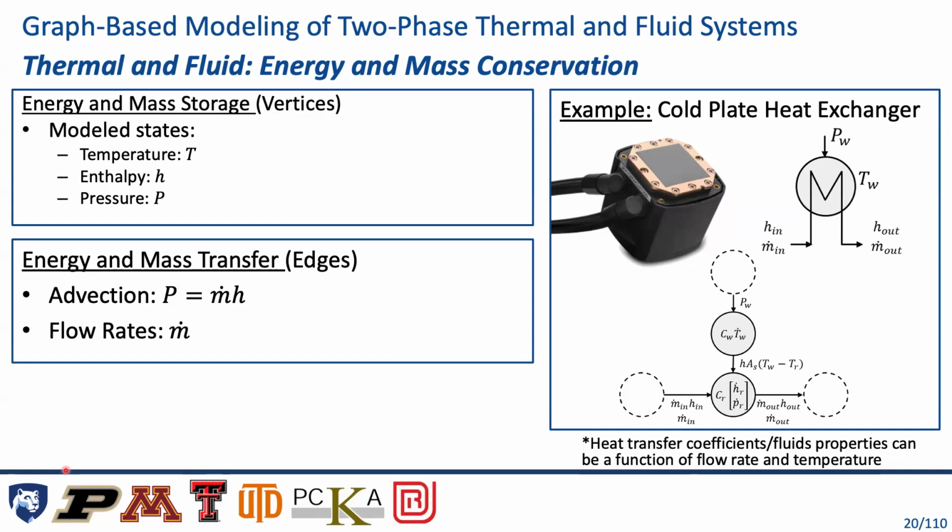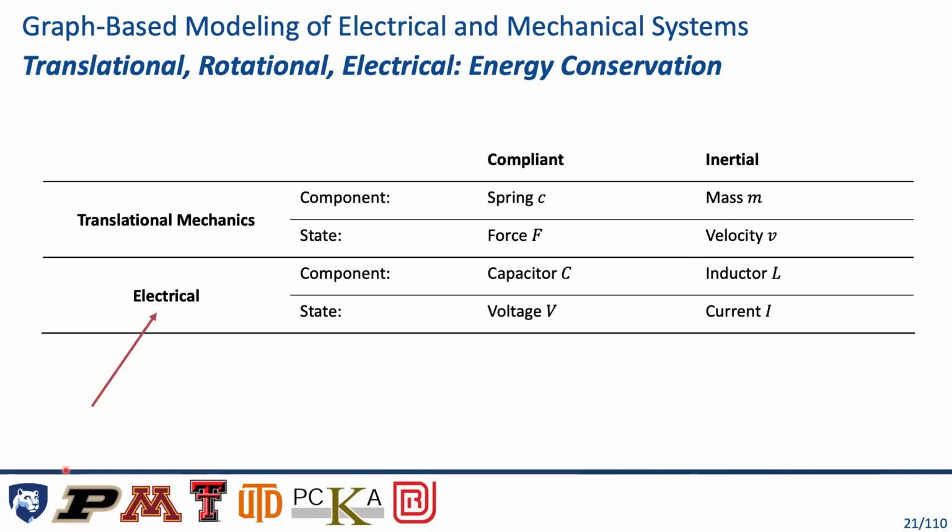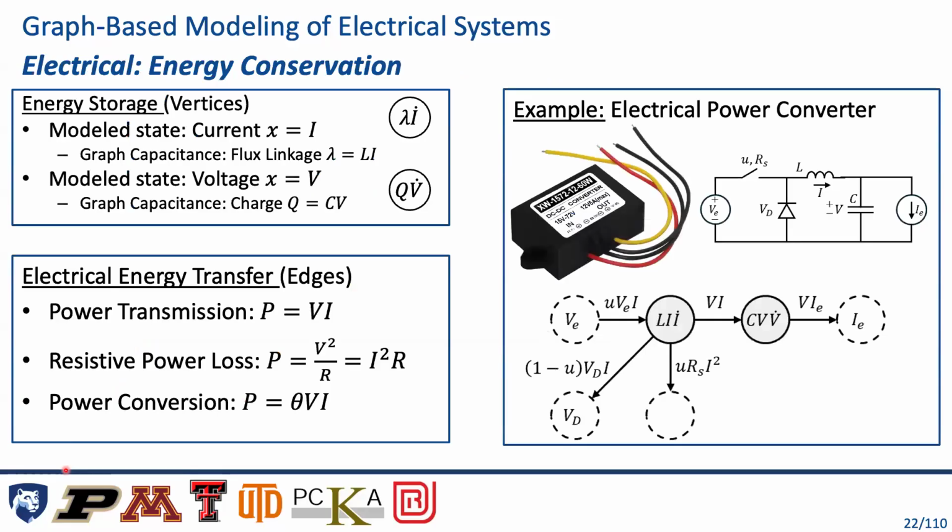In here, we model both the enthalpy dynamics as well as the pressure dynamics all within one node on the graph. We've also done a healthy amount of work on electrical and mechanical systems. These are modeled in fundamentally the same way. I hope a lot of us are familiar with the electrical and mechanical analogy, right? Springs are a lot like capacitors, masses are a lot like inductors, and so on. We really exploit that analogy when we model these two types of systems.